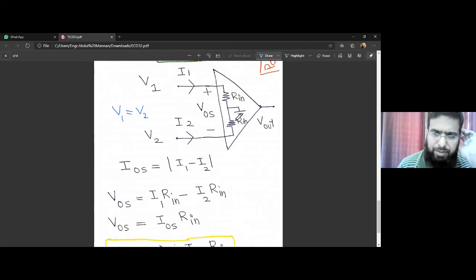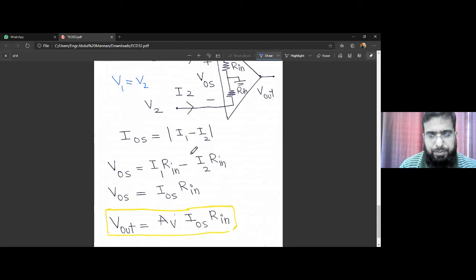Because this voltage is measured such that we apply the red terminal at positive voltage and the black terminal at ground, but here we have the opposite polarity, therefore we put a minus here. If you would measure it from here to here, we would put the red terminal here and the black terminal of the voltmeter here, that would also be positive. So here we are measuring a positive voltage with respect to ground, therefore it is negative.